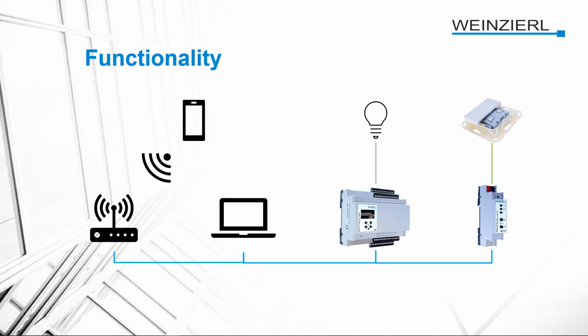The KNX IP router connects the KNX twisted pair network with our IP network, and from our KNX twisted pair network we are initially only looking at one push button sensor. This push button sensor is parameterized in such a way that it should switch a digital output from the multi-IO on and off. But how exactly does the telegram now go its way?